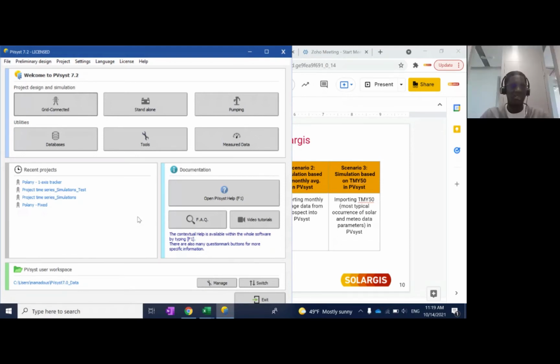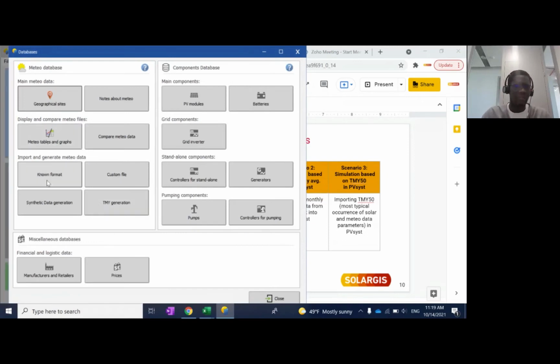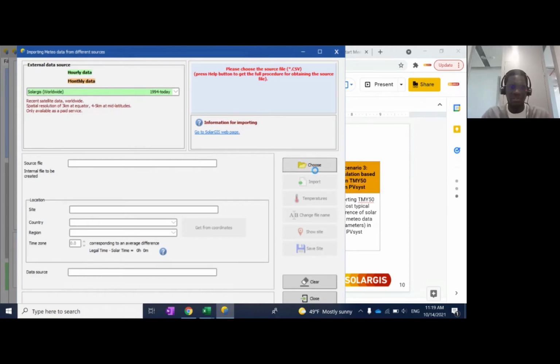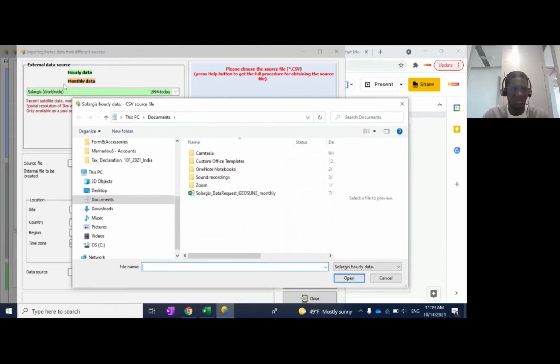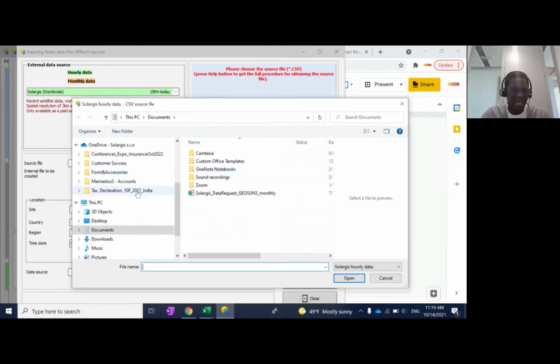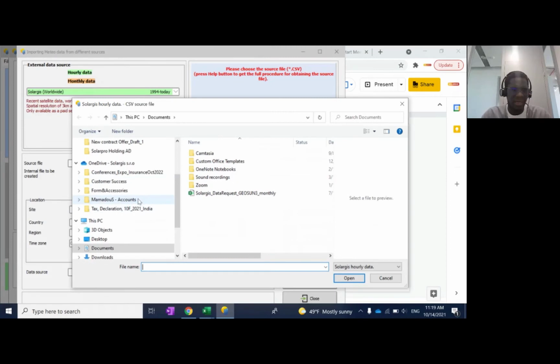Okay, perfect. Thanks, Marta. So that said, in PVsyst, you first need to create the meteo file. You simply have to go to database, and then extract your file. In this case, it's going to be TMY P50. Yes, perfect. And before that, make sure also that you're using the representative data source here. The TMYs are hourly data, that's why we use hourly here. And then I'm going to simply extract and load my files.